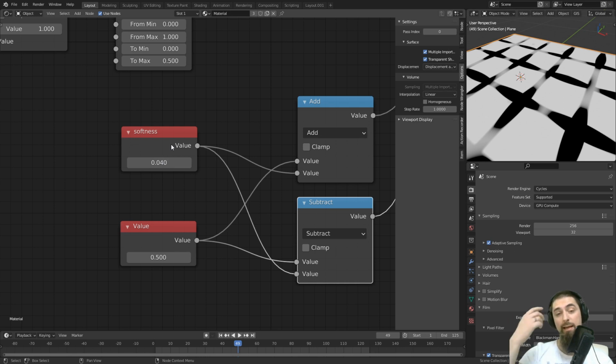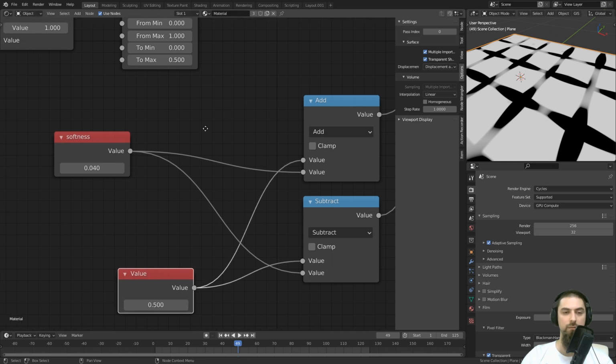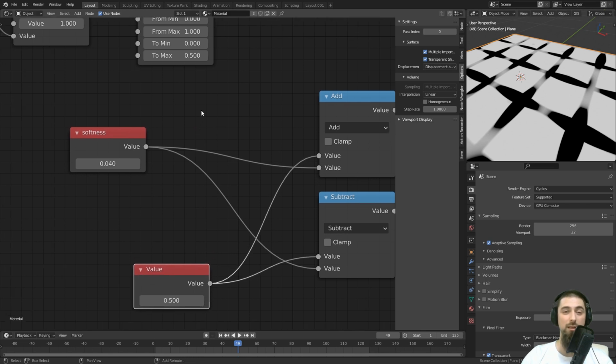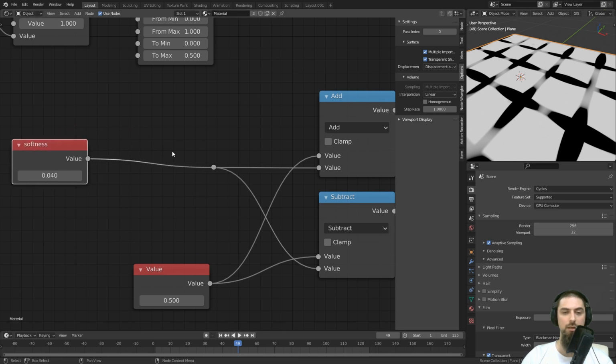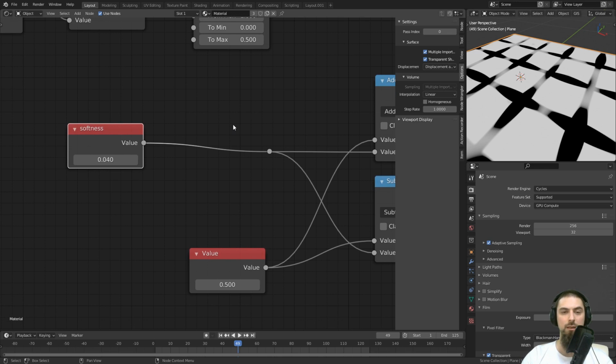So I want to clamp it. And I can actually do that when I add controls to the node. But I want to do it here, just safer. And I want to do it with clamp. So let's add a dot. It's shift right mouse button to do that.